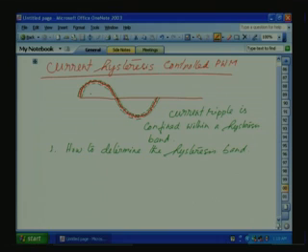Previously, for sine triangle PWM, the PWM switching frequency was FC. Here we don't know what the switching frequency is. This is very important.